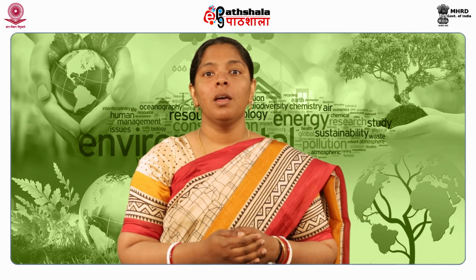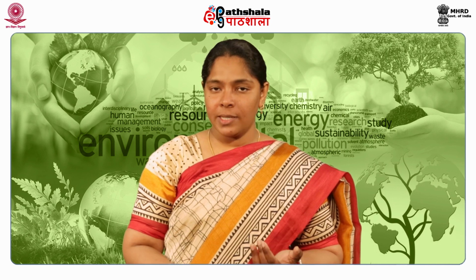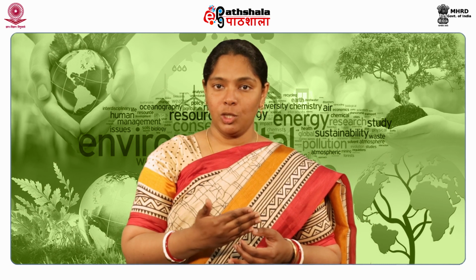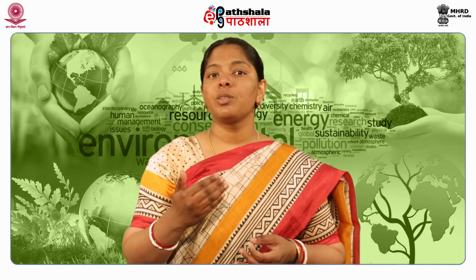There are different ways of enhancing the biogas production. It involves the use of additives, recycling of digested slurry and slurry filtrate, variation in the operational parameters like temperature, hydraulic retention time, particle size of the substrate, and use of fixed film or biofilters.